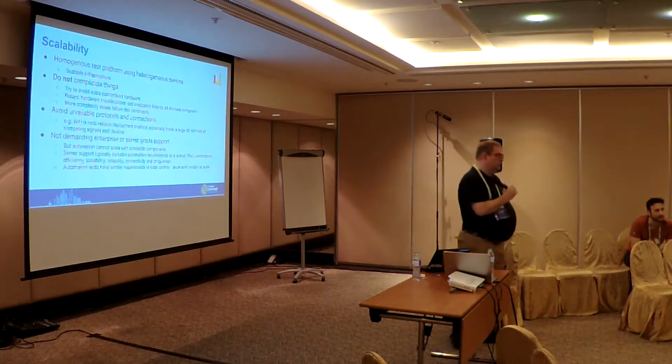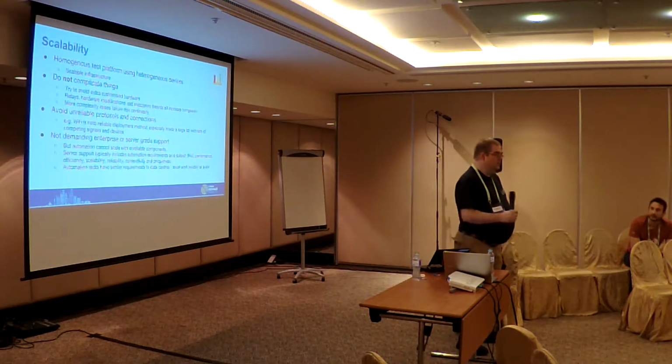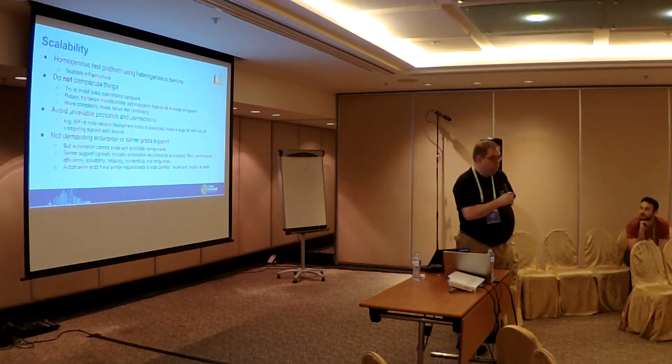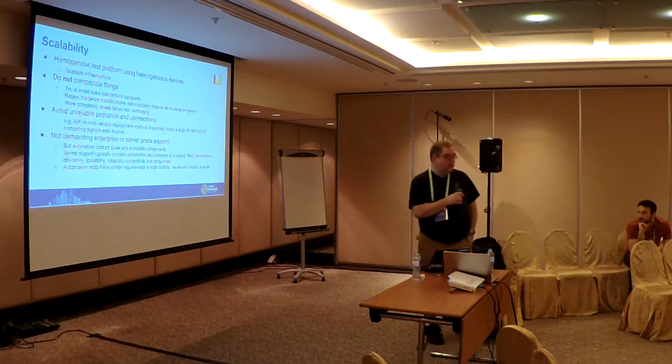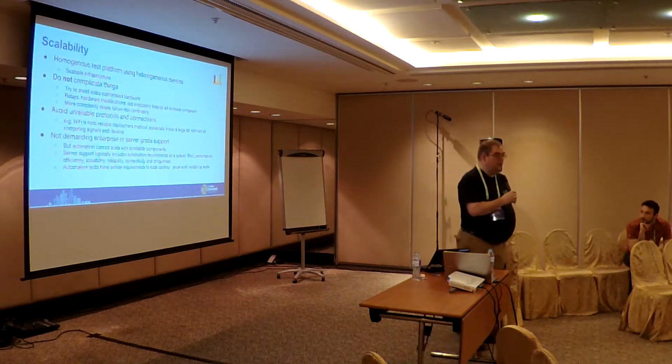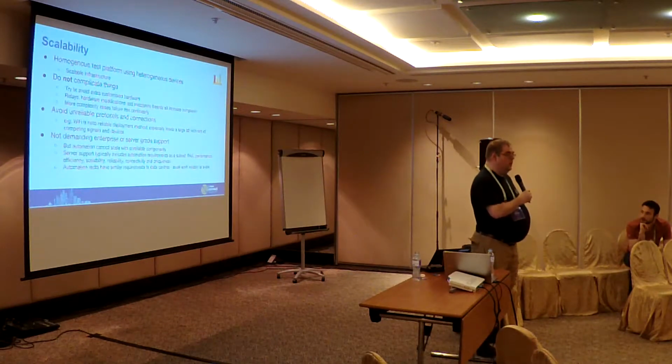That said, IoT, that's the way we're going to have to do it. But again, this comes down to testing, and it's all about single device as opposed to thousands of devices. If your device works fine on your desk in a nice, quiet office somewhere, where you might just see a couple of access points, and the access point you're using is right next door, then fine, it'll be absolutely reliable for firmware updates.